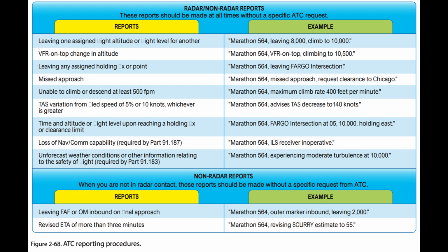Other equipment installed in an aircraft may impair your ability to safely operate under IFR. If a malfunction of such equipment, e.g., weather radar, affects any safety or IFR capability, report should be made as stated above. When reporting GPS anomalies, be very specific and include the location, altitude, and duration of the anomaly. Deliberate GPS interference or outage areas resulting from pre-approved government tests will be disseminated in NOTAMs. These outages should not be reported to ATC, as this condition is known and not an anomaly. See also AIM 1-1-13.